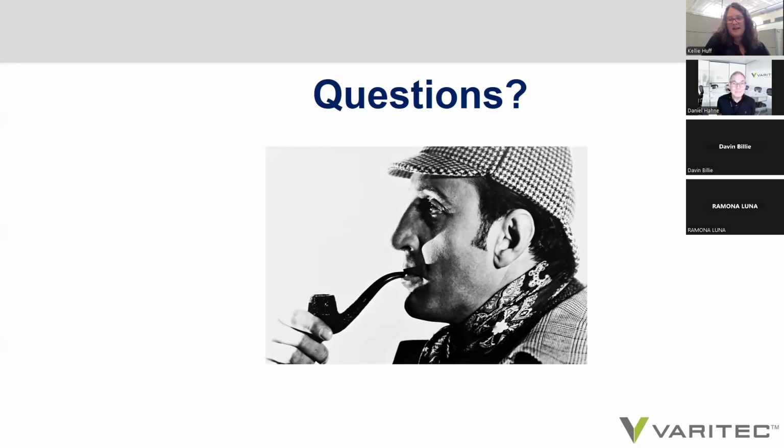And another question just came in. So Daryl, if you wanted to stay on while Dan answered this, if anybody else wants to stay on, if not, feel free to head out if you have to leave right at 1. But with a small classroom building having 10,000 square feet, would you anticipate a DOAS unit would be needed for a split system heat pump fan coils?